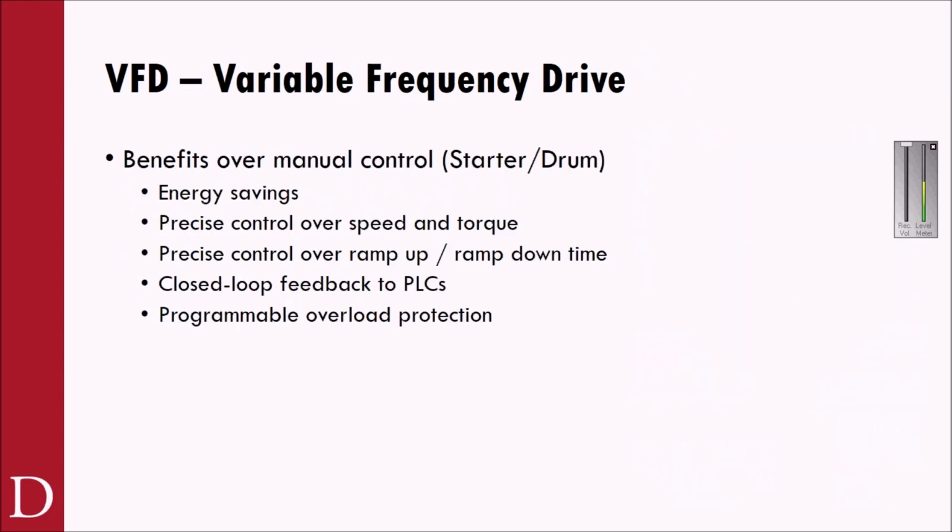So some of the benefits over a manual control like a starter or a drum switch: energy savings. I have precise control. I can ramp up, I can ramp down as needed. I don't need to run full speed. I have precise control over speed and torque.